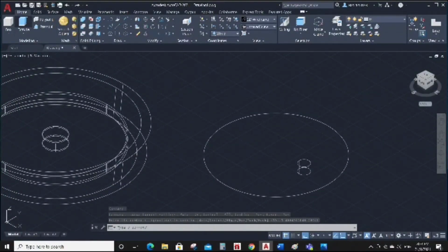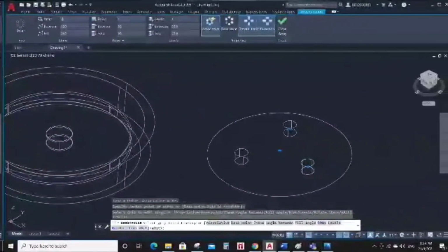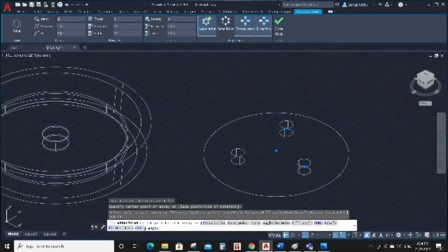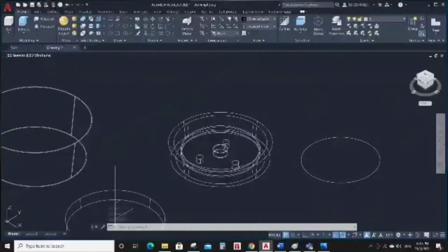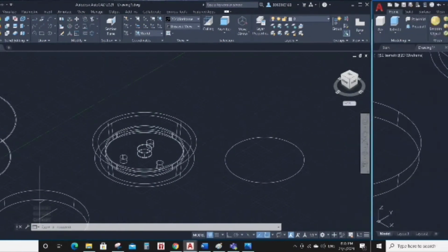Then I made a stand for the plate. Firstly, I use a circle of radius 110 mm, following the plate radius circle. Then I made a circle with a radius of 10 mm and a height of 15 mm, and put it inside the circle, and the distance between the center points is 60 mm. And I use the command polar array to make the objects at the same distance. After that, I move the part into the middle section.